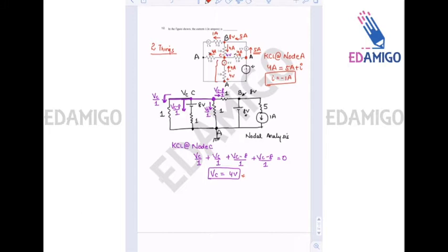So by applying Ohm's law, we can find that in this branch, the current is from bottom to top, 4 ampere. In this branch, it is 4 ampere, C to A, in this direction. In this branch, B to C, current is flowing from top to bottom, 4 amperes, and then KCL will help me to find out the value of the result. So I is equal to minus 1, right?